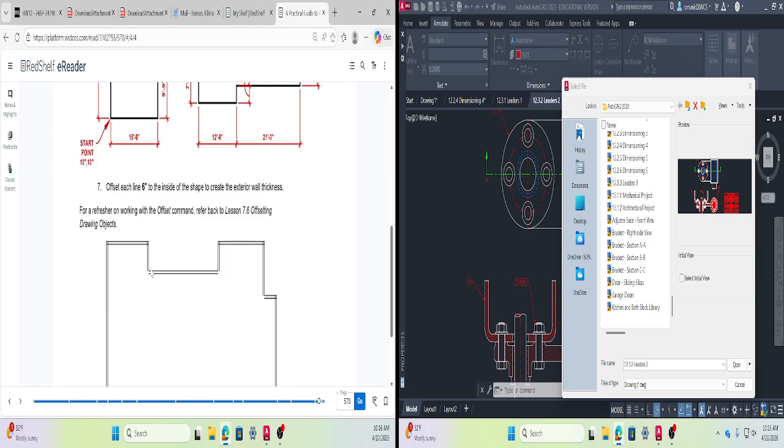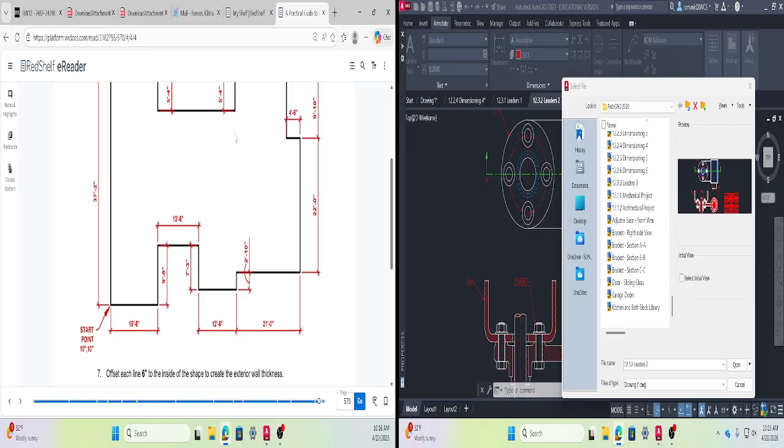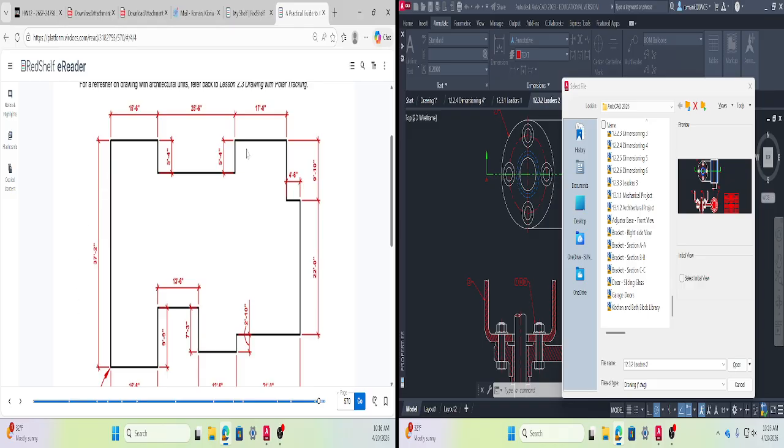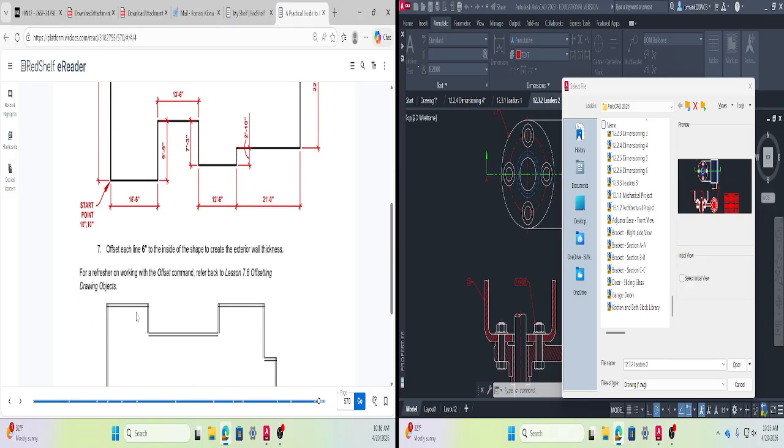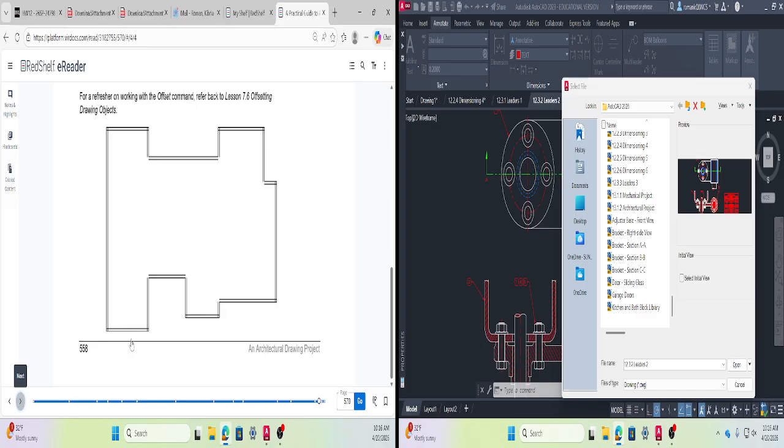You guys remember the offset? So what does the offset do? You're going to create another layer, right? Another layer of your existing layout, meaning the outline. So once your floor plan outline is drawn, then to create the wall, you need another layer, and you'd like to use the offset, okay? So that's what we're going to do on Wednesday, obviously, okay?